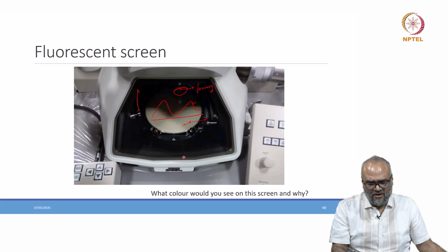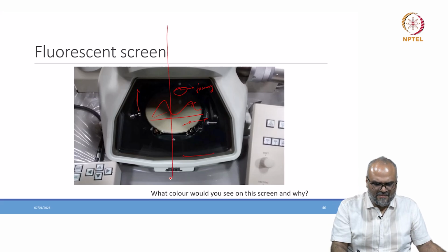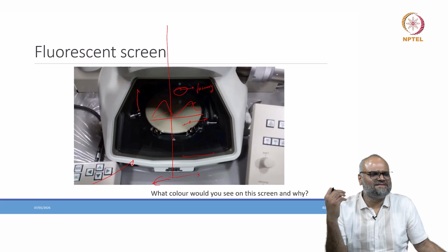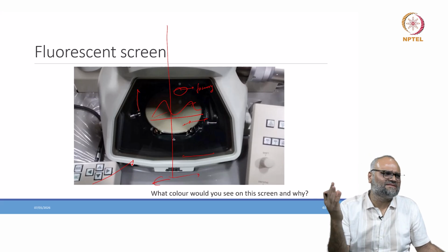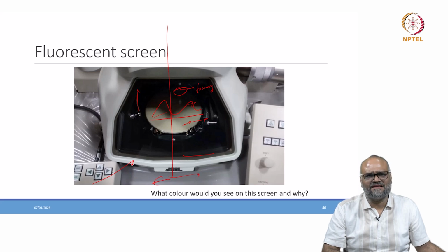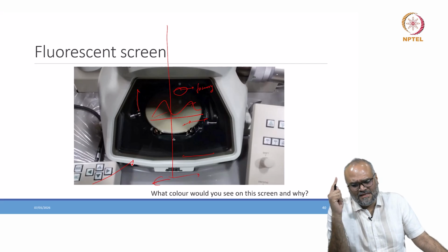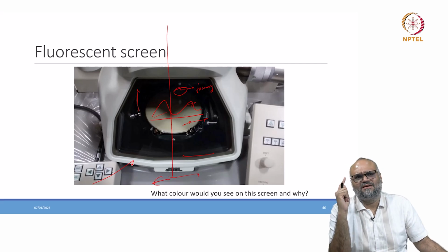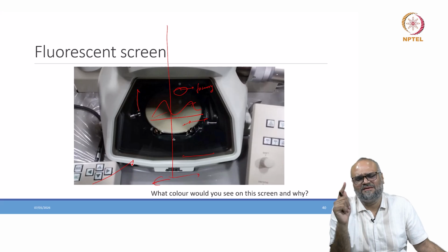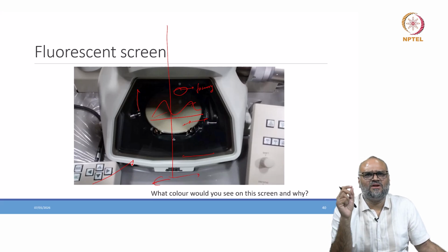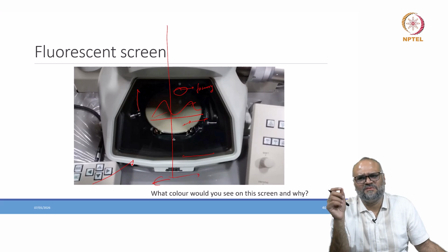Once I have an on-axis camera which is aligned with the optic axis of the electron microscope, or sometimes you have some retractable cameras, or you have an EELS camera, you typically use a CCD camera. I'll just show you the basic construction of how a CCD camera looks like in the next slide. You record the information. There are a few important parameters here. You should know what kind of dosage you can allow onto your camera, what are the exposure times, what is the appropriate imaging condition such that you do not damage your CCD or your CMOS camera.